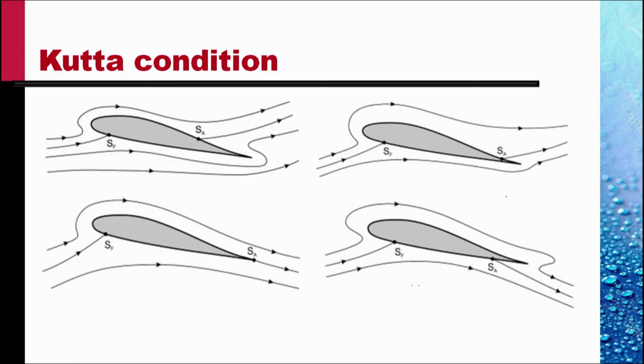To repeat, the aft stagnation point here with zero circulation. I change the value of circulation and this point starts moving down towards the trailing edge. At one specific value of circulation superimposed, that is, on the potential flow that we obtained without the circulation, we keep on adding a vortex. And when the vortex strength reaches a certain value, the stagnation point is right at the trailing edge.